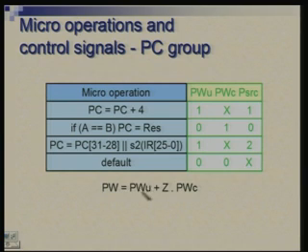If PWU is 1, PW becomes 1 irrespective of what is it we have here. But when PWU is 0 and PWC is 1, then it is Z which dictates what we get here. If both are 0, then again Z gets ignored. So, basically I need one AND gate and one OR gate. The controller will produce these two signals, and with the 2 gates I will derive PW, which gets connected to the PC. All right, is that clear? Any question about that?